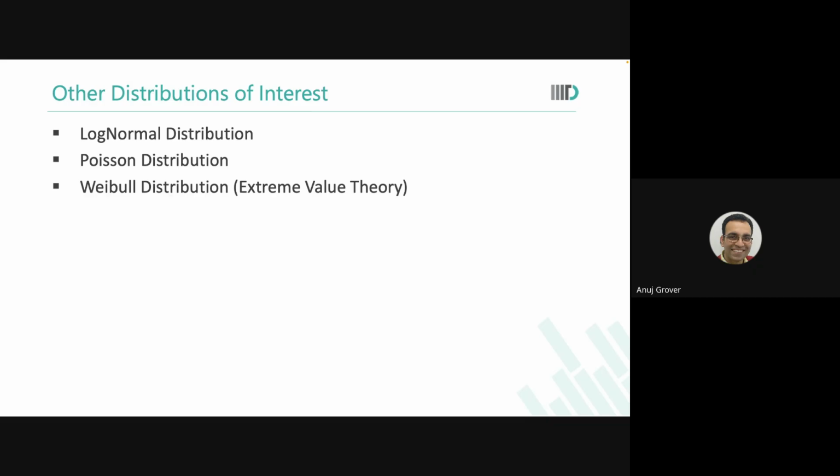See, the basic processes are Gaussian. VT is Gaussian in nature. But the impact of VT on leakage is not linear. It is exponential. So other distributions also become relevant. Log-normal distribution, Poisson distribution, and extreme value distributions like Weibull and Gumbel become important in the design verification processes that you will need to build there.